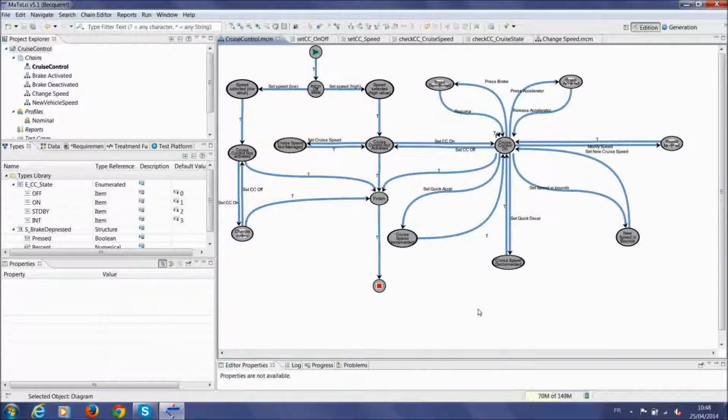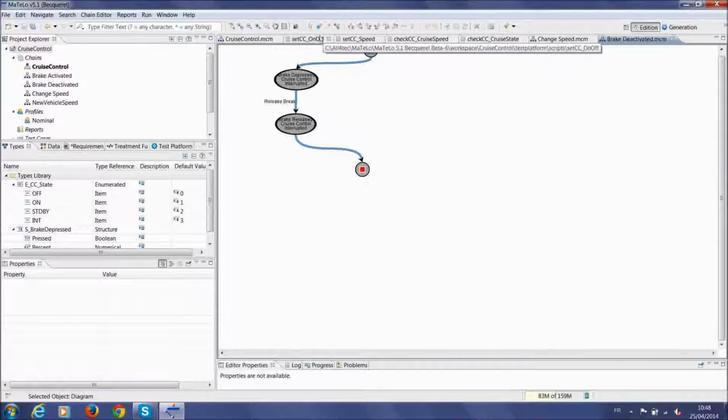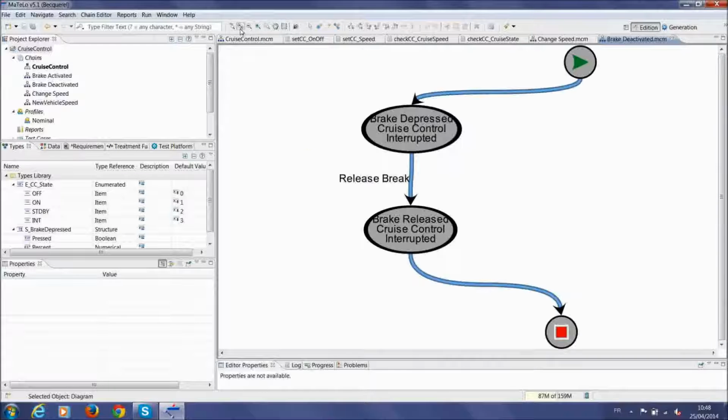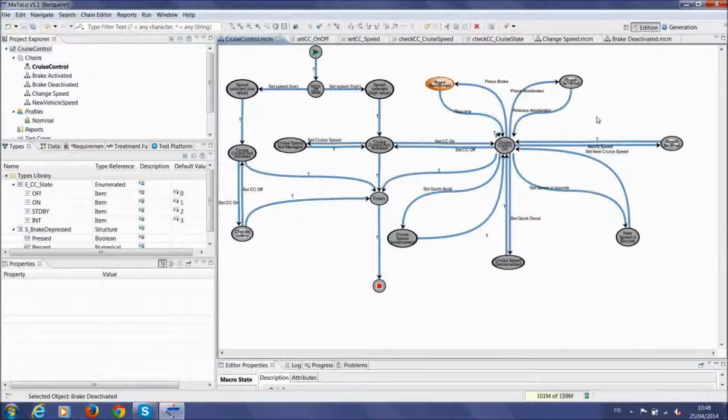To associate one or several requirements to a transition, select the Transition tab and then Requirements. Choose a requirement that you wish to associate from the requirement library, and drag and drop it in the editor window under the title requirement.